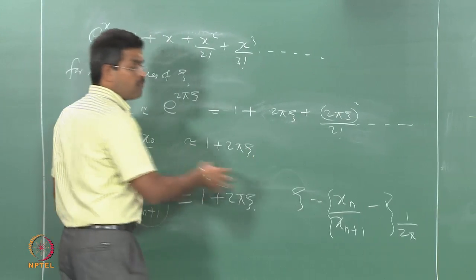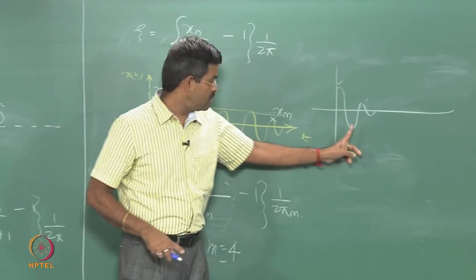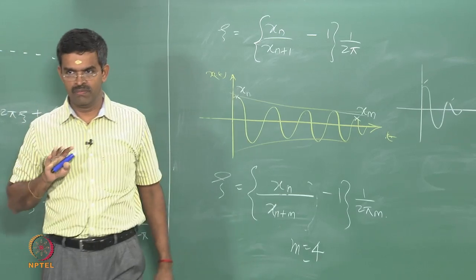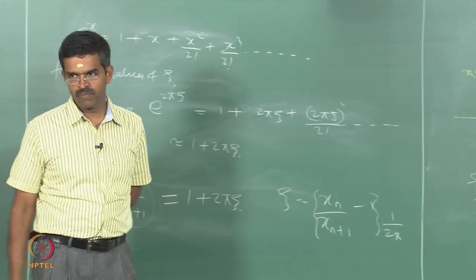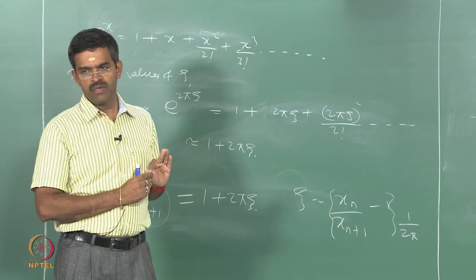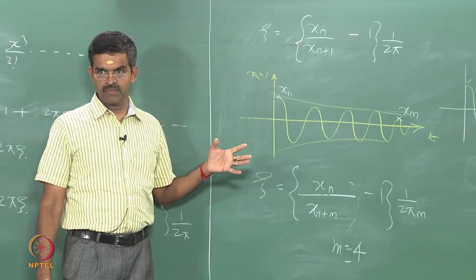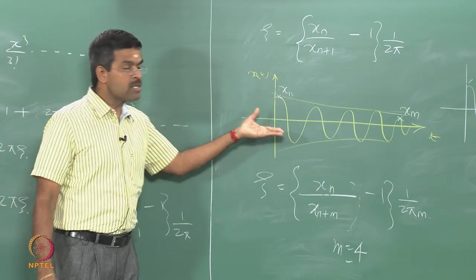Now, with this zeta if you plot, you must get back either this equation or this figure from the original function, which is equation 7. That is how it is done. Any doubt here? So, we discussed damped free vibration system. Now, one may ask me a question, if the vibration is free, where is the damping source coming from?